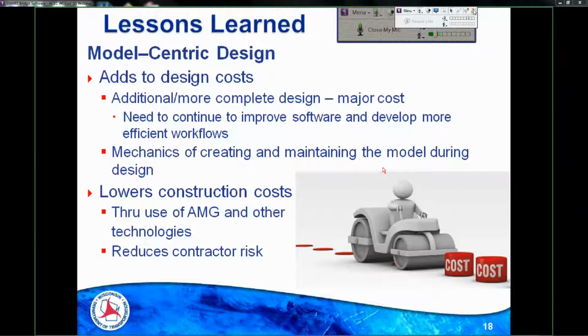That is what they're doing. And when we talk about contractual elements of a design model, to me, the surface model is going to do the best job of representing design intent. Because I've had people ask me in conversations like this, well, if contractors want to use longitudinal break lines to build their road surfaces, and it's the longitudinal break lines that they always use, for those contractors, they may look at our surface model as a guide, but they're building their own models off the break lines, right? Why do we even give them surfaces?